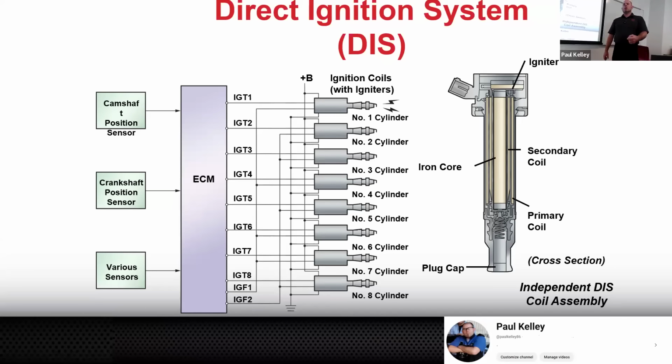If something chews them, or if a two-legged varmint, that's us, pokes them the wrong way and ruins the insulation, now water gets in it and corrodes it, right? Or if the wires fall on the header because you absolutely had to have the header to go bang, bang, and now your wires are laying on the header and they get burned up, right? If you leave the car pretty stock and everything's routed the way it's supposed to, there should be no problem with your wiring harness, like ever. Accidents and these types of external issues cause problems with wiring.